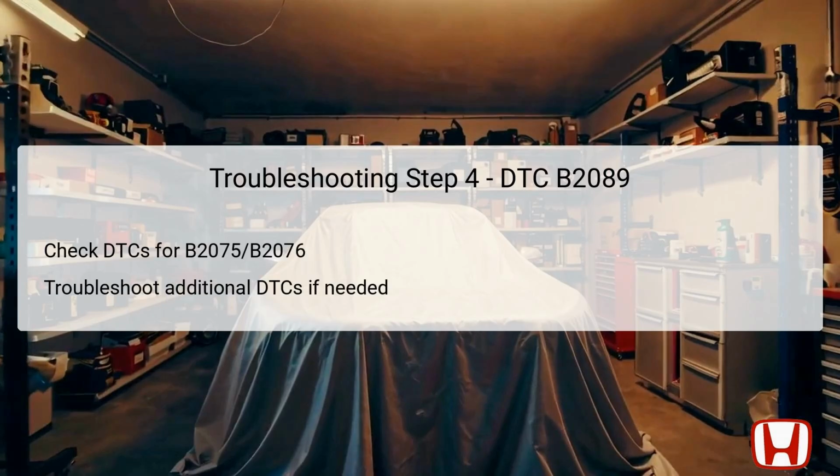future issues. In this step, the focus shifts to checking if any additional DTCs, specifically B2075 and/or B2076, are present along with B2089. If these codes are solely present, troubleshooting should prioritize addressing these specific DTCs. Each code indicates issues related to the sliding door mechanisms, with B2075 focusing on the rear left door and B2076 relating to the rear right.